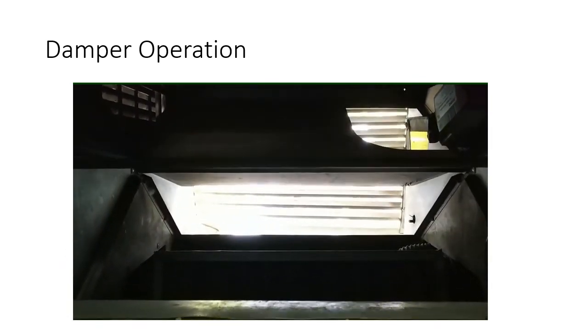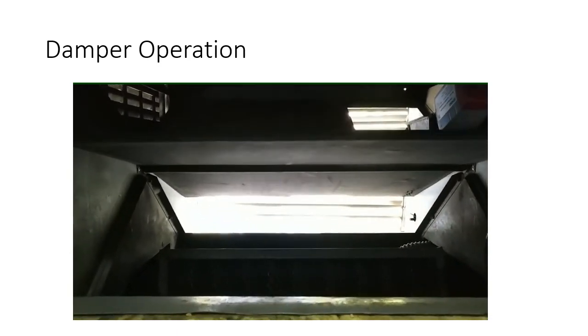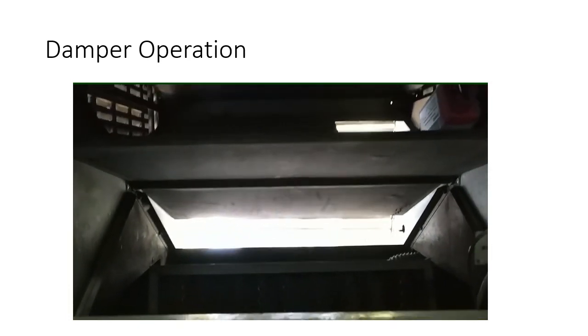The damper has one stepper motor, called the damper motor, which gives a 180-degree movement of the damper on the y axis. We have to ensure that the damper closes face to face with no gap. If any gap is found, kindly use a foam type gasket and fill the gap so that fresh air leakage can be arrested. Your damper should operate only as per the desired condition.